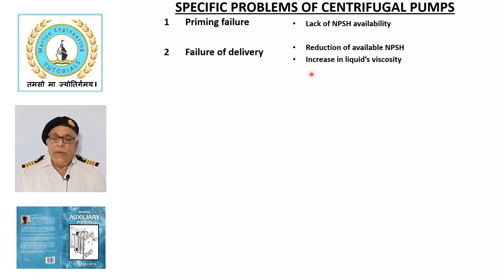Delivery of liquid may also fail if the viscosity of the liquid increases beyond pump specification. This problem may be dealt by increasing the liquid temperature and bringing down the viscosity within pump's design capacity.